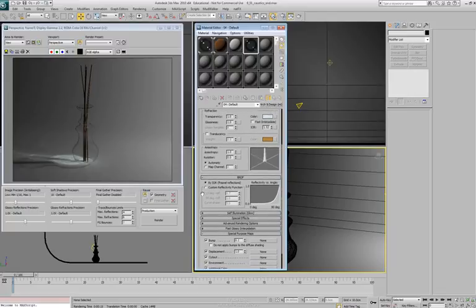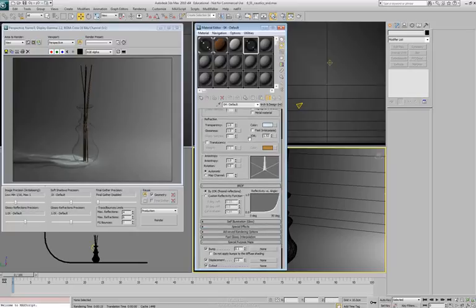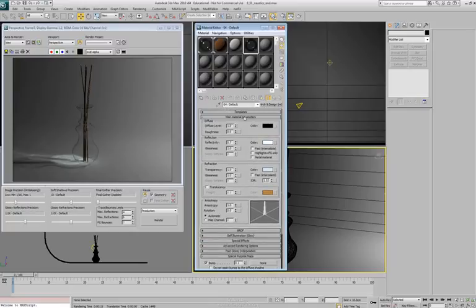So in here, we have our options. We're going to see one that says we can actually use it by our IOR setting. This is our Fresnel reflection. So it's actually using our number, the IOR up here, and it's doing it automatically for us. Now if we wanted to do custom, we could do a custom. We could set our 0 degree, which is our viewing angle in front of us, our 90 degree, which is basically perpendicular, it's on top of the object. And we could adjust our parameters in here so that we could take our curve for our horizontal, and we can knock that up and down. We can take our 90 degree and bump that in and out. And we can actually change the curve shape to pull that in further and to pull that out closer. So you can manually adjust that if you want to. If you understand how the IOR works really well, it's an option if you're trying to tweak it. Your best bet is just to leave it on the automatic and just let those numbers determine that for you.